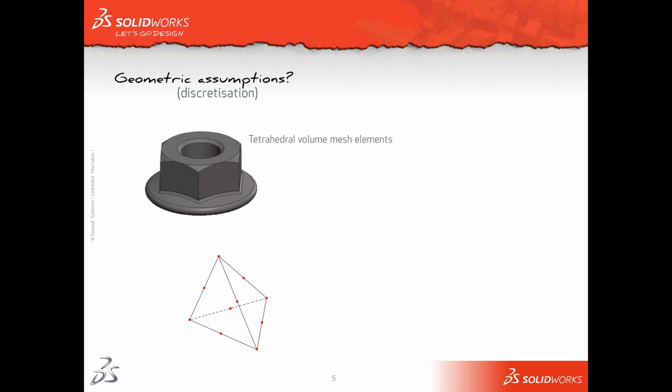Hopefully, if you can get your head around it, you should be able to see we've got 4 main nodes dictating the 4 vertices of that solid mesh element. And what SolidWorks is going to do is break our model down into a number of these elements, and later on the solver will be calculating the displacement and stress results at each of these nodes.